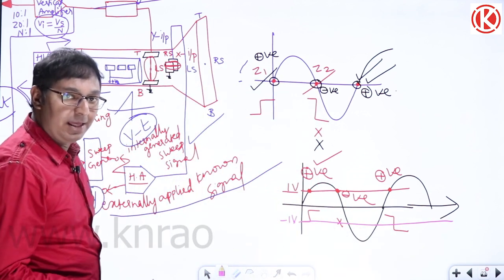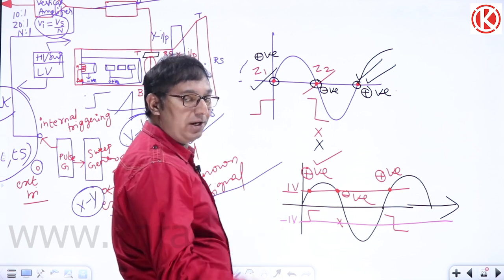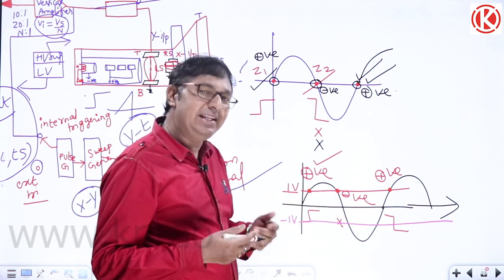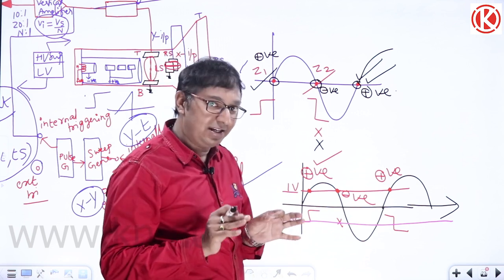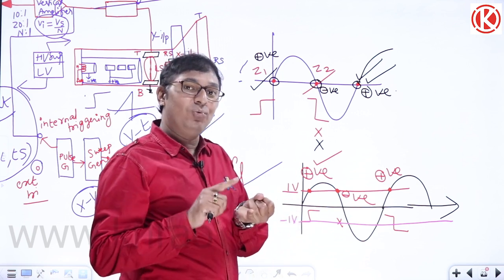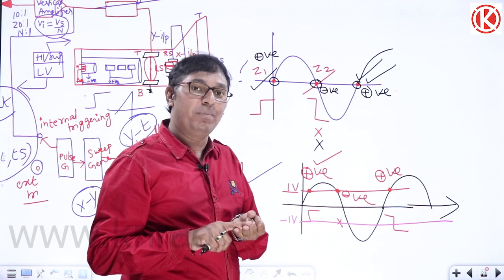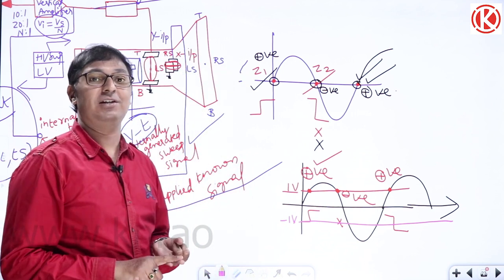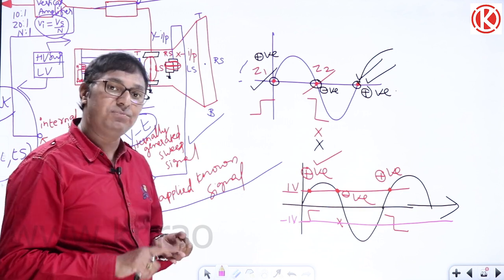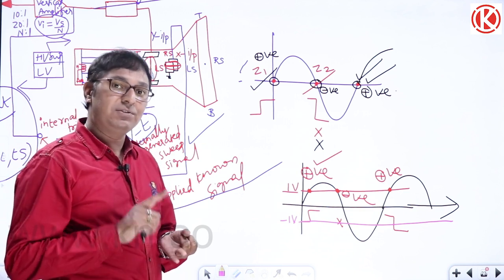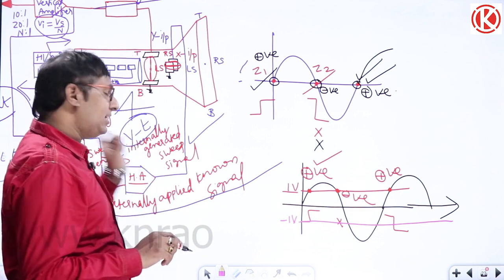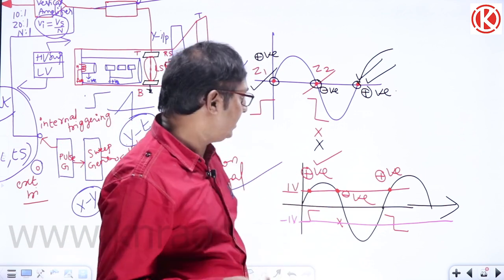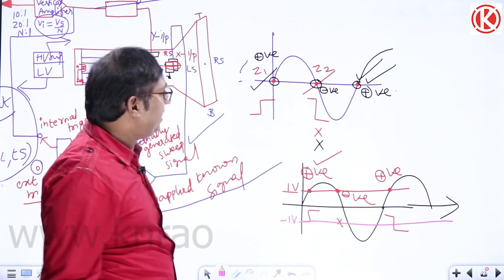Minus 1 volt you can take, and you can select the triggering slope. Even a negative triggering slope can be selected. Okay, is it clear? Triggering voltage and triggering slope have to be selected by the user. You might not have done it in your labs. Then only will the sweep generator produce the sweep signal, after my pulse generator produces the pulse. Is it done?